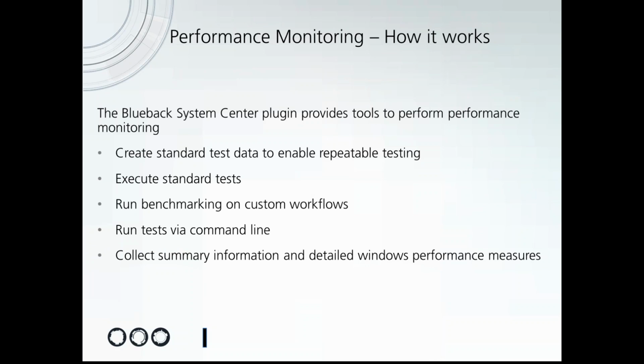So just a little bit of background on how the performance monitoring works. The System Center plugin, which you install beside Petrel, contains a bunch of tools for driving the performance monitoring. This includes creating standard test data, which means that we can run tests with the exact same data to ensure that we get repeatable measurements that we can compare like for like. Using the plugin, we can also execute standard tests, like loading into shared memory or realizing a seismic cube.